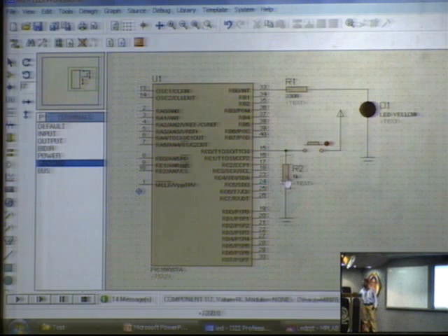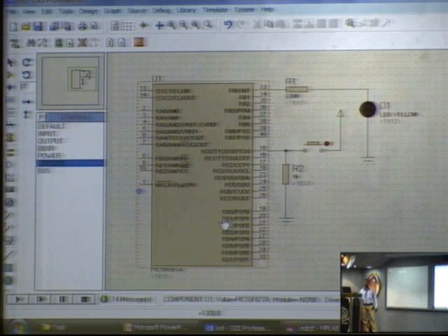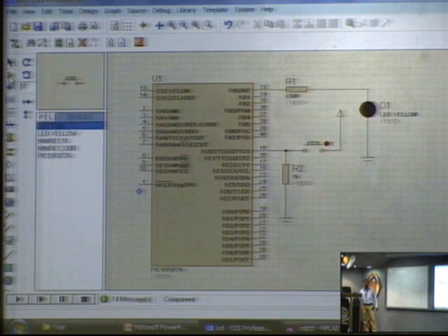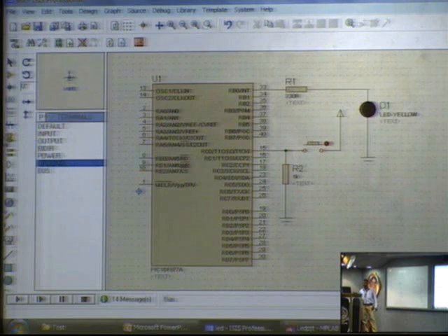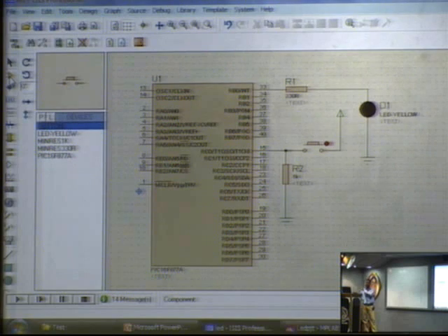At this moment I need to move the position of the resistor. For example, I need to move the LED little rightwards. So what you should do? Or at this moment you need to add one more component. So how we will add? For adding component as well as moving the component, again you should go and click the component mode, because here you had selected only terminals mode. Whenever you want to change some component or move component, you need to again go and click on this component mode. Then only you can make any changes in the circuit.